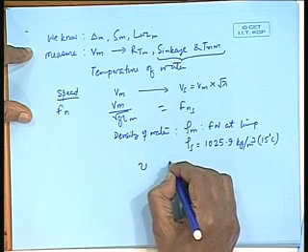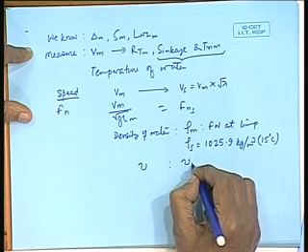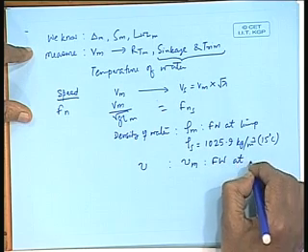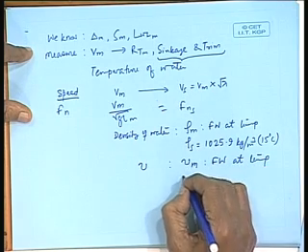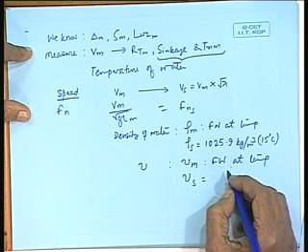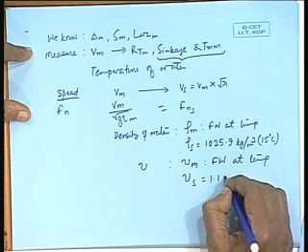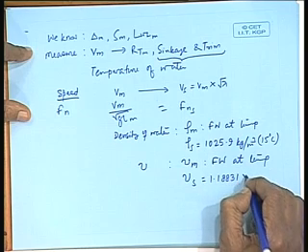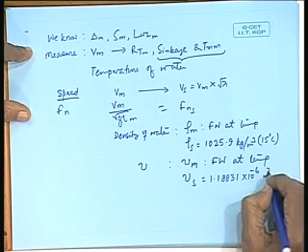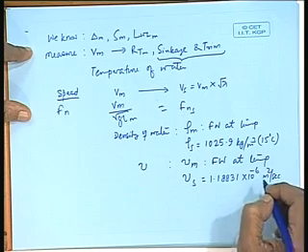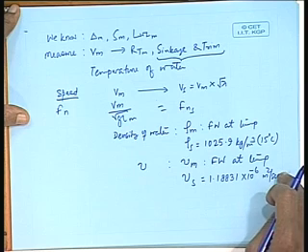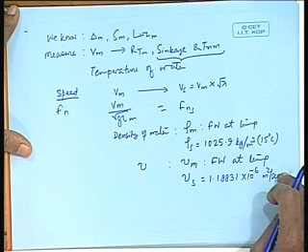Kinematic coefficient, similarly for the model it will be fresh water at measured temperature, and for the ship it will be equal to 1.18831 into 10 to the power minus 6 meter square per second. This unit we have seen yesterday. So, this is the standard kinematic coefficient of viscosity at 15 degrees.